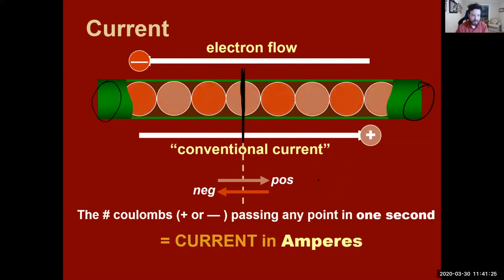So if you had a voltmeter and an ammeter, and you wanted to take a measurement off of a light bulb, the only way to actually take that measurement would be to put the amp meter right here in line.